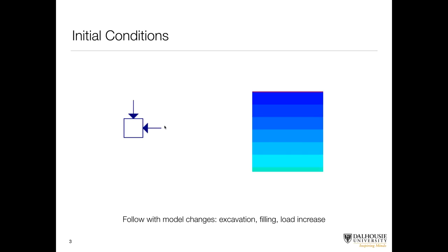We have a vertical stress and a horizontal stress. And we use the K ratio, or the ratio of horizontal to vertical stress, to represent those stresses. And typically we might say the stresses, say at 100-meter depth, have a horizontal stress of say 10 MPa and a vertical stress of say 5 MPa. So we use explicit values.